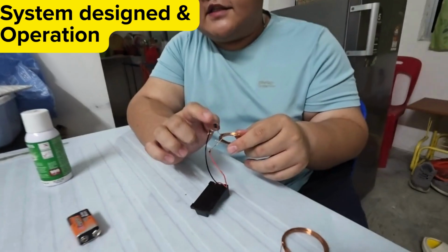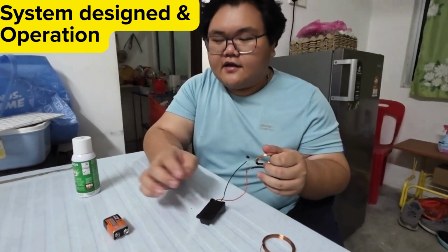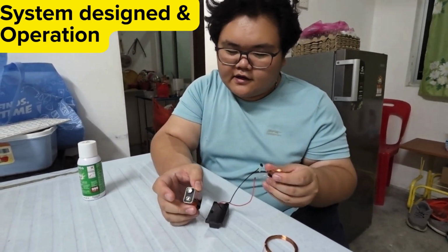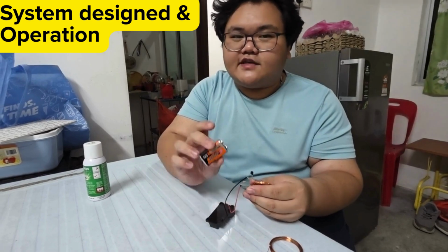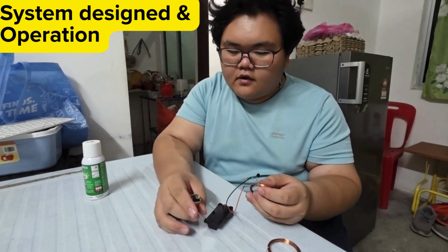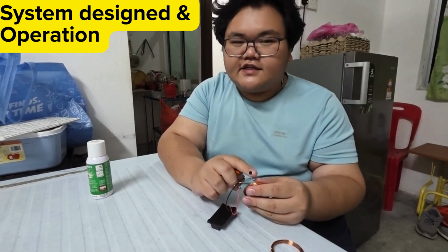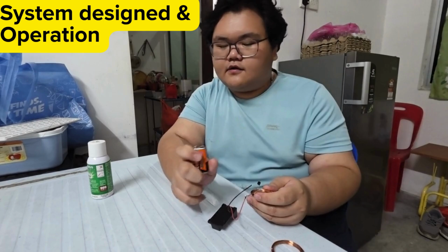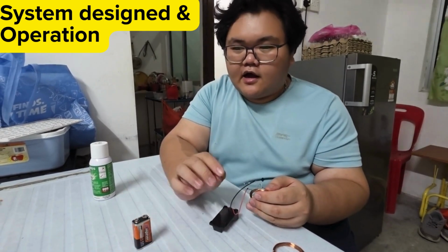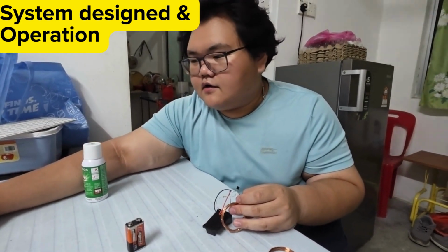What the transistor does is switch the DC, because the voltage that we use is DC, and we know that in order to create a time varying magnetic field we need AC. So the transistor will change the DC into AC by consistently switching the DC voltage on and off.